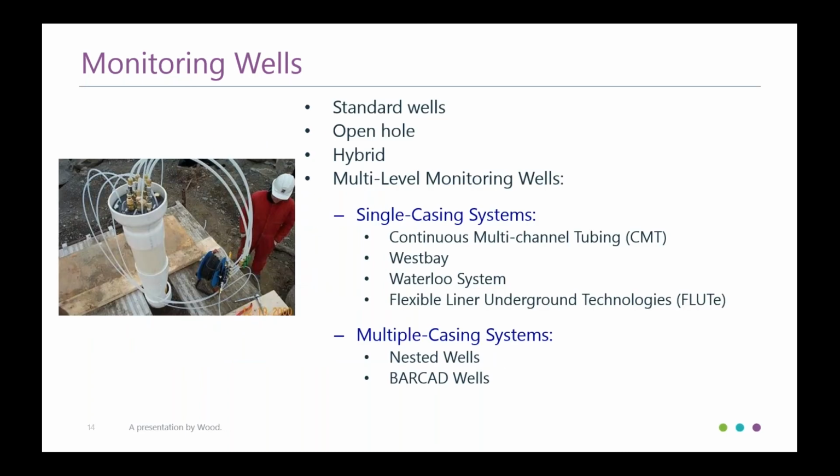Types of monitoring wells: standard wells, PVC with slotted screen. Those screens generally are put in 10-foot sections, but you can modify those to whatever section you need. People just generally put them in at 10-foot. And as you're refining your investigation, you're going to want to think about what size screen meets the needs that you have. Hybrid wells, a well that would span both the overburden and bedrock.